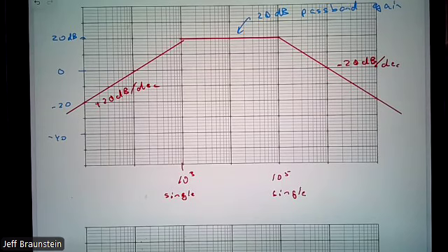Do our RLC circuits like this one not have a slope of minus or plus 40 dB? Usually I thought RLC has the 40. So if the transition from low pass or high pass, if we're doing output across the inductor or output across the capacitor, then we have a change of 40 dB at the resonant frequency, underdamped. If it's overdamped, then we just go through the math like we've done before. I should point out, I didn't explicitly say that this is an overdamped response. We will look at the underdamped response. It won't be part of your task, but we'll talk about it in class because it is an important circuit.